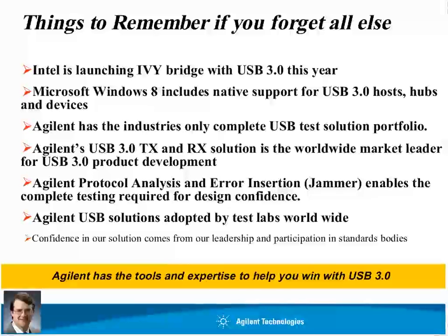The protocol capture and decoding on a scope is a complementary technology that can be used to isolate problems. When you find the error, you do cross-triggering with the protocol analyzer to capture what's going on the bus with the scope, and then you can verify that it isn't a PHY problem causing this, that it's actually a firmware, software, or digital problem.